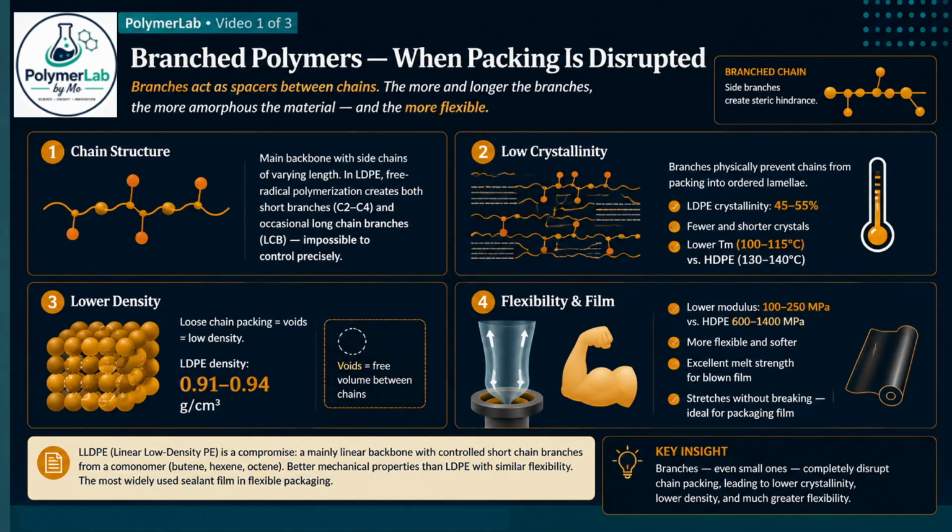Its long chain branches give it exceptional melt strength, the ability to stretch and hold its shape during processing before it solidifies. This is why LDPE is the first choice for blown film. The inflated tube of molten plastic that becomes packaging film needs to be stretched without breaking, and LDPE does this brilliantly.